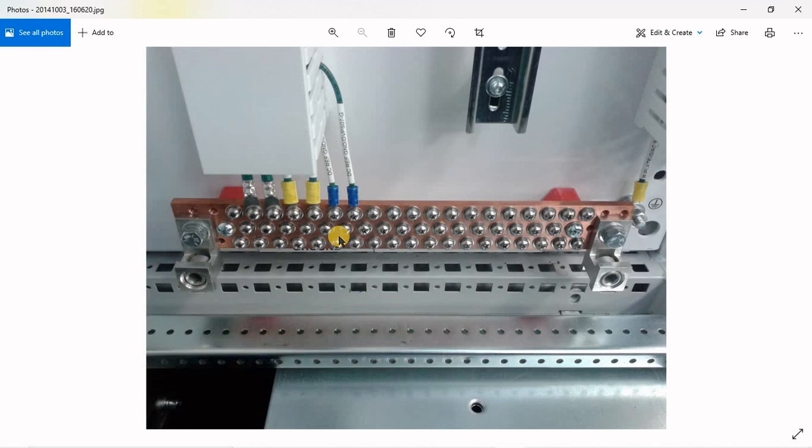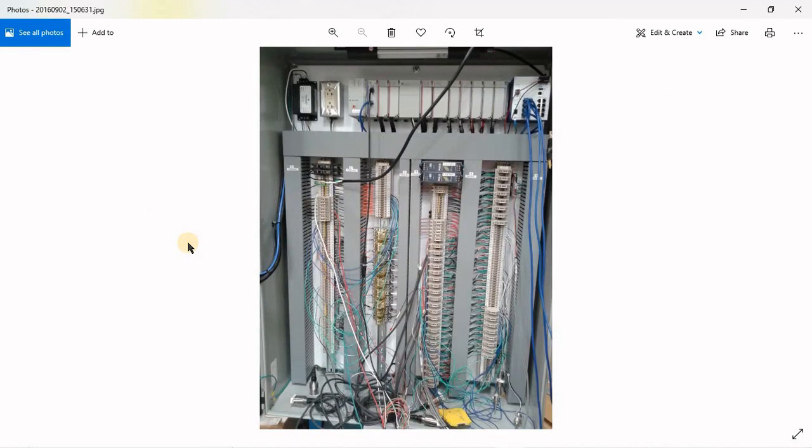We prefer to connect them outside the cabinet, when they are connected in the control room. All the ground from the instruments and all the ground from the electric, we connect them there. Some codes or some companies allow you to connect them inside each cabinet, at the bottom here, so you connect them here and then you go with one connection. So check, especially for your DCS or PLCs, what code you are following and the manufacturer's recommendation.